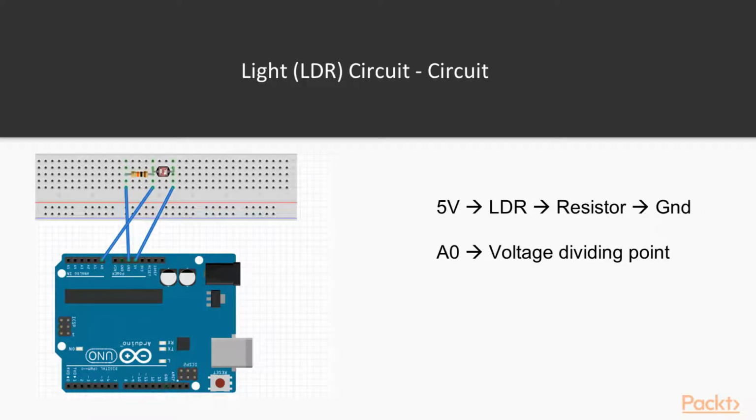So you have an Arduino Uno, we have a breadboard, you have an LDR, you have a 10k ohm resistor and 3 jump wires. Alright, perfect. First connection, 5 volts to your LDR's one end. Second connection, the other end of the LDR to the one end of the resistor. Third connection, the other end of the resistor to your ground.